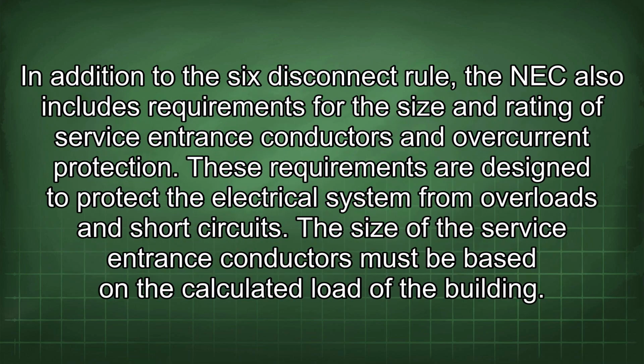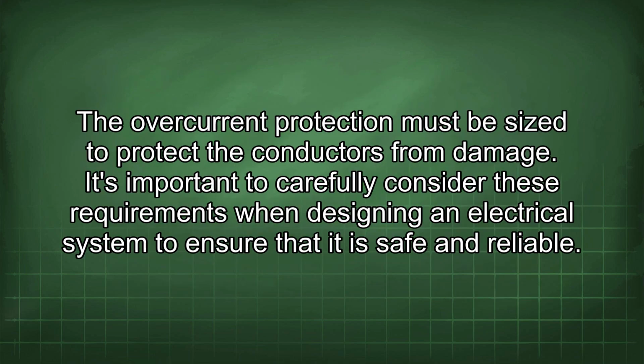In addition to the 6 disconnect rule, the NEC also includes requirements for the size and rating of service entrance conductors and overcurrent protection. These requirements are designed to protect the electrical system from overloads and short circuits. The size of the service entrance conductors must be based on the calculated load of the building. The overcurrent protection must be sized to protect the conductors from damage. It's important to carefully consider these requirements when designing an electrical system to ensure that it is safe and reliable.